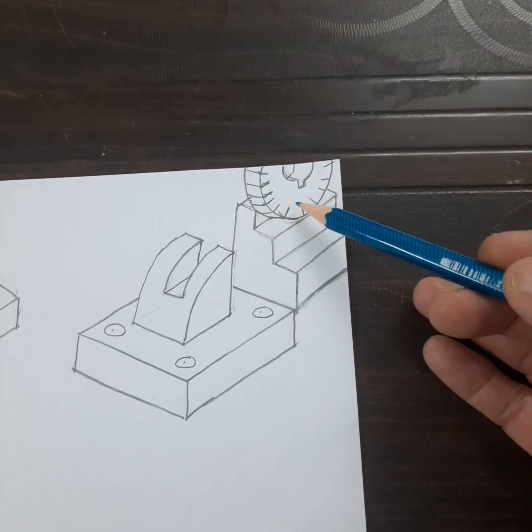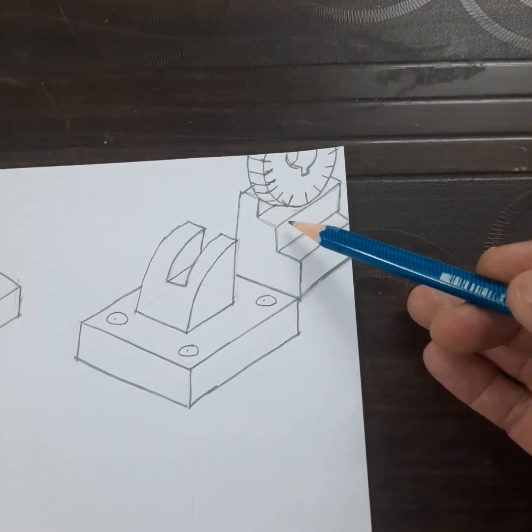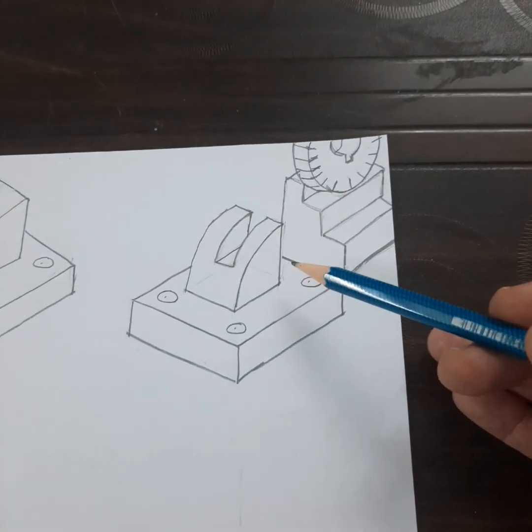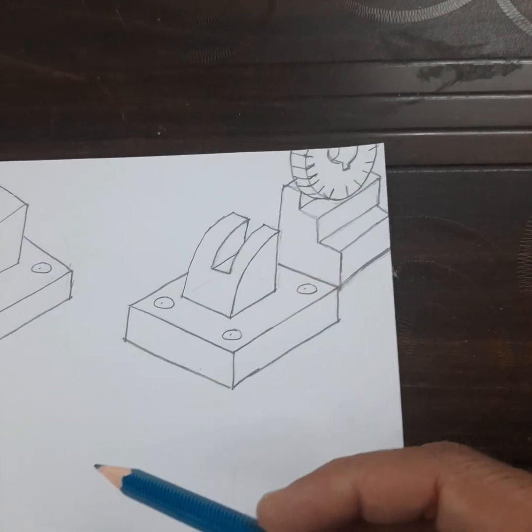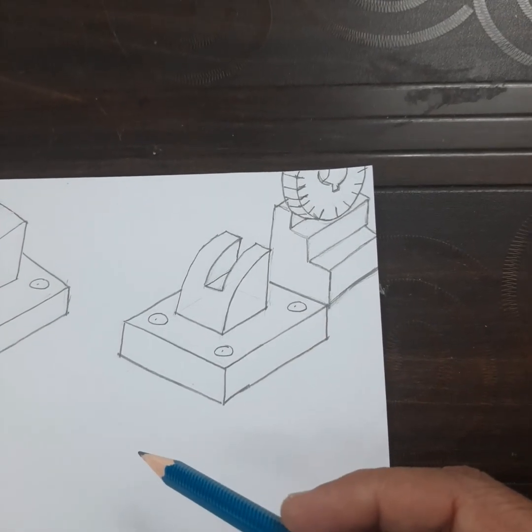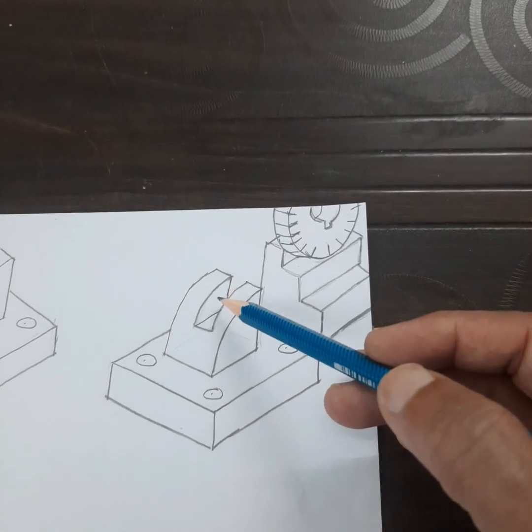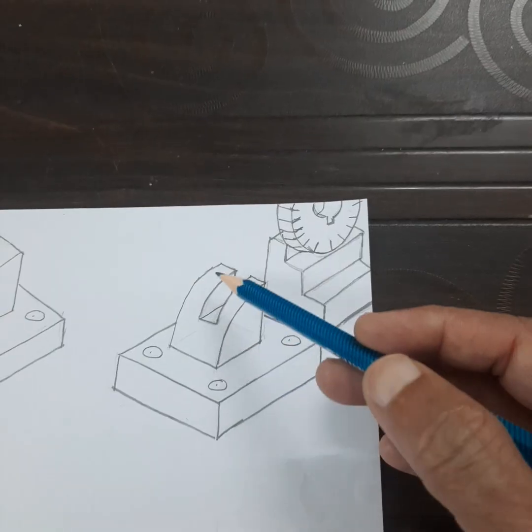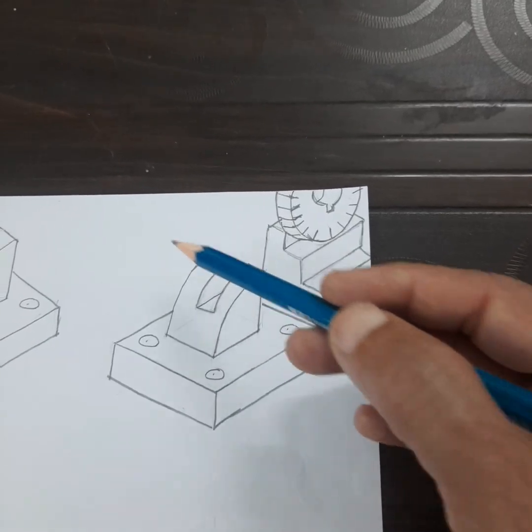So once the cutter is positioned in this way using the setting block, then the only movement given to the table of the milling machine is the longitudinal movement. So when you move the table in the longitudinal way, the required slot is cut with the required depth and with the required positioning with respect to this direction.